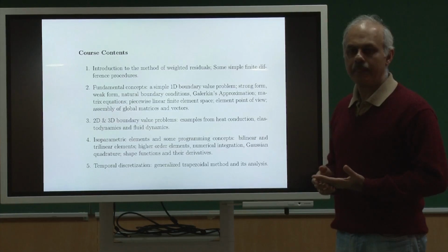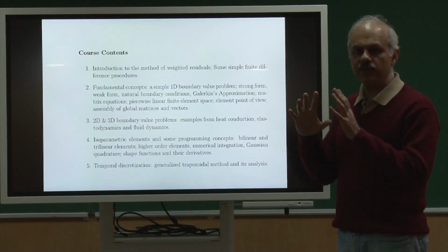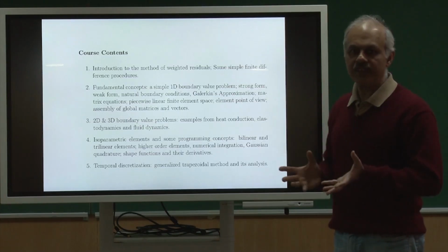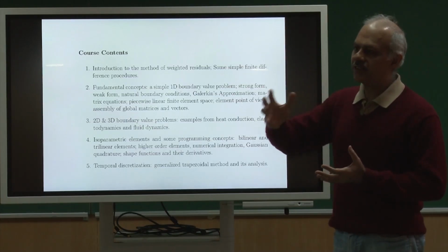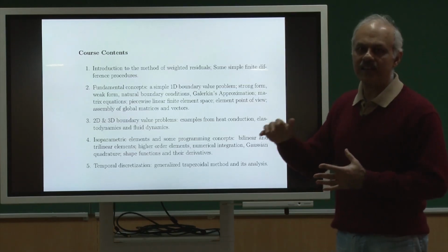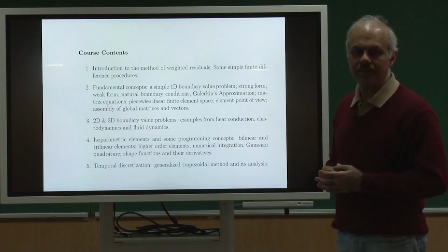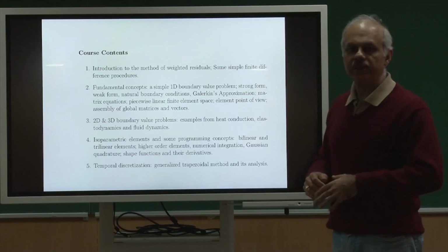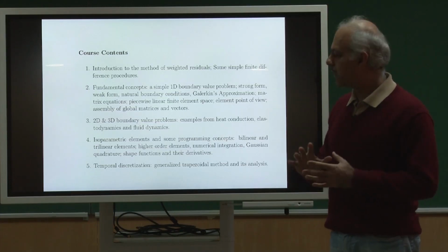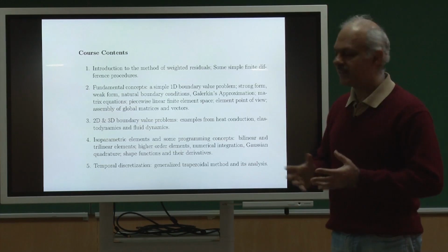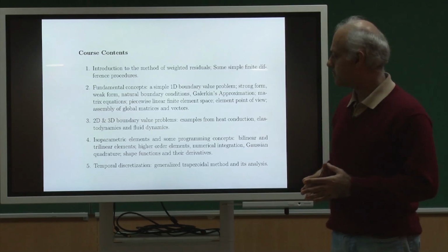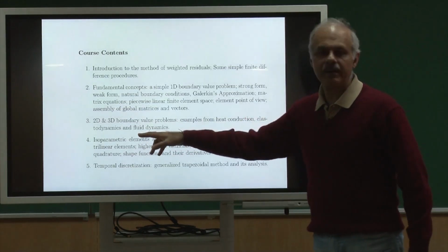Think of the following. Suppose I am interested in looking at flow past a sphere, and to represent the sphere I could say, well, the surface will be represented by higher order panels, not just linear panels, not just straight panels. Okay. But the flow I would like to represent with linear elements. So, I could have higher order elements for the surface and a little bit lower order for representing my solution. So, that is not isoparametric.